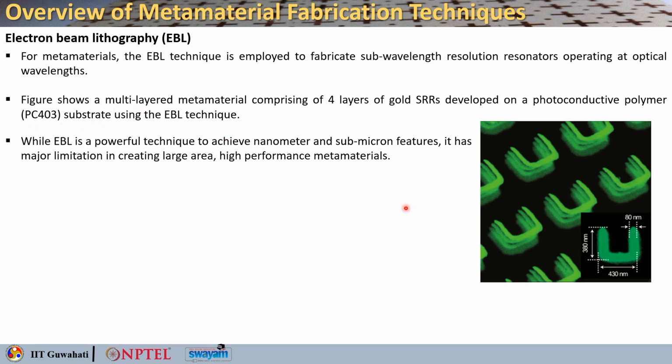While EBL is a powerful technique to achieve nanometer and submicron features, it has major limitations in creating large area and high performance metamaterials. For example, writing an area of 3 mm by 3 mm would take up to 24 hours.